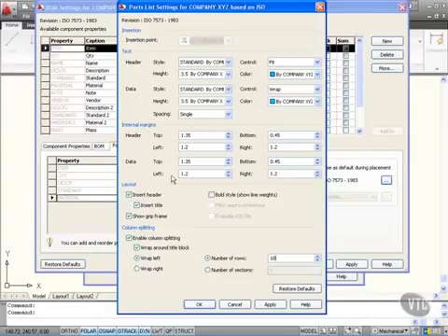Now what I'll also look at are my internal margins here. My header, top, left, bottom and right have all been set up accordingly. I'm going to change these slightly. I'll make that 1.5. Going to make that 0.6. I'm going to make these slightly different so that when I bring a parts list in, not 6.6, that's a bit too big, 0.6. Like so. Left, I'm going to make 1.5 as well. And right, I'm also going to make 1.5 as well.